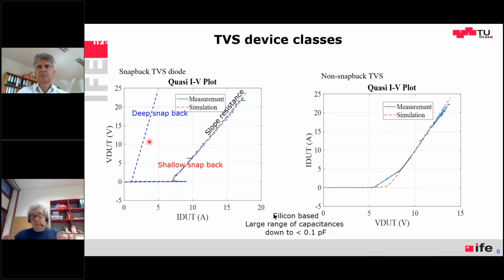But if you're broadband, then you cannot do that, because if your amplifier goes from 10 mega to 1 giga, you can put an inductor there to get rid of the low frequencies below a couple of megahertz. But then you're faced with this protection problem, and one has to very carefully look at the data sheets of which TVS devices can handle your power without causing too many harmonics. It's a very difficult design question, and all manufacturers of ESD protection devices are trying to improve their designs to produce fewer harmonics. But it is a difficult question for certain situations.